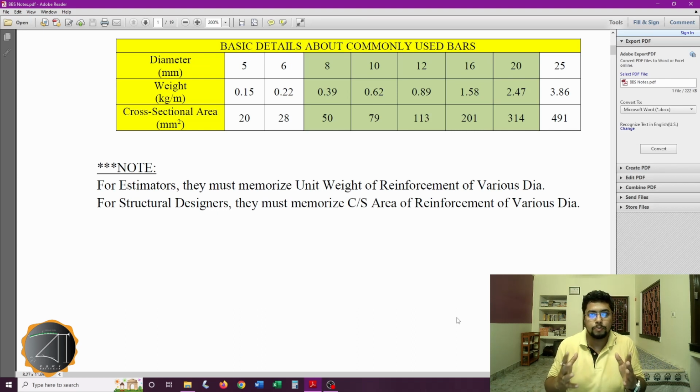It sounds pretty critical, right? Like say, in a particular portion of a slab, we are designing for the mid span. From the view of a structural engineer, we are only concerned about the reinforcement at the bottom portion, and near the support we are much more concerned about the reinforcement on the top portion due to the change in the nature of the bending curve.